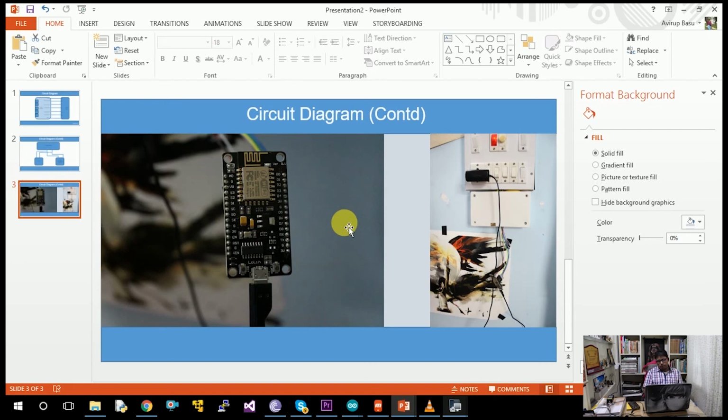However, you may fabricate the Node MCU along with the relay module in a single PCB and make it a black box kind of structure with a few inlets and a few outlets. However, this was done in just a day for me to perform some tests during long hours of operation. Till now my Node MCU is tested for around 72 hours of continuous operation, and I haven't faced any heating issues, neither with the relay nor with the MCU. I will say it's very dependable as far as home automation is concerned.